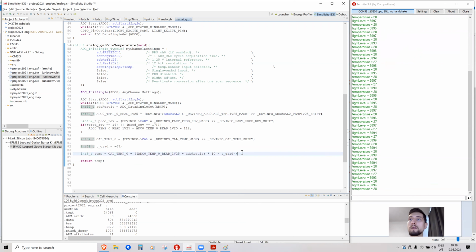So this is a trick that everybody uses in microcontroller embedded programming, since the chips usually don't have floating point unit. And even if they have it, it's more expensive. People just try to use integers instead of floats. And as we did here, it's usually pretty easy. If you have some floating point coefficient, you just multiply it with so many tens until you get rid of the point. And the top part you also multiply by the same number.